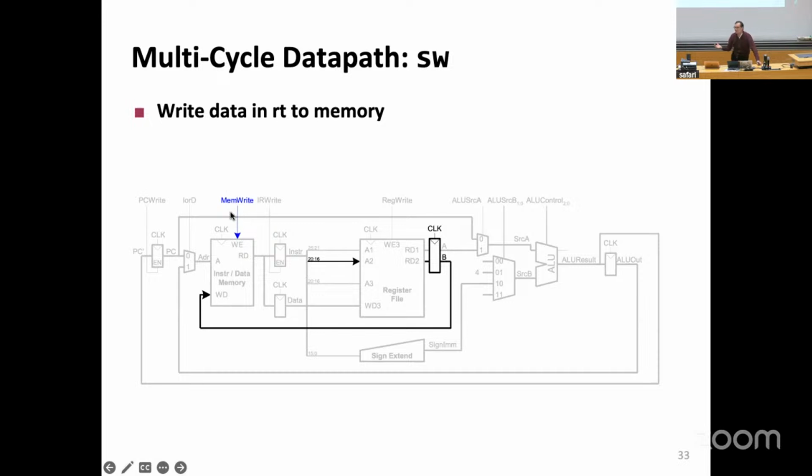So this is very similar to what we have done with single cycle. We moved from load to store, if you remember over there. Similarly, we have the entire data path almost. We just need to read another register, which is going to be the data that's to be written by the store to the memory. And we need to provide the data path element and storage for that, this register. And then we need to take it and write it to the memory at the address that is computed the same way the address of the load is computed.